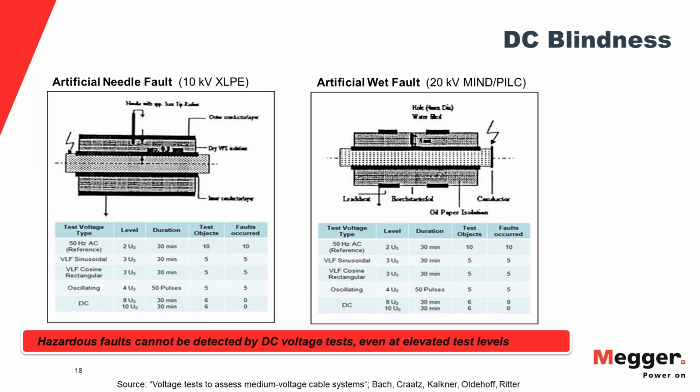Because DC is a unipolar voltage, you're pumping the insulation full with charge, and this forms space charges, concentrated amounts of charge which are trapped. And even if you properly discharge the cable, you will not be able to evacuate those trapped space charges from the solid dielectric insulation. The main reason for that, just as technical background, is that when we're talking solid dielectrics like polymers, polymers are chain molecules.